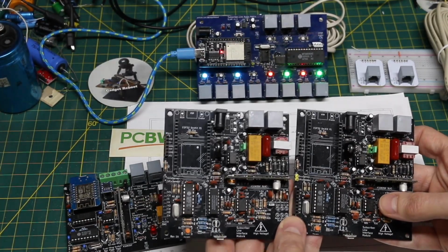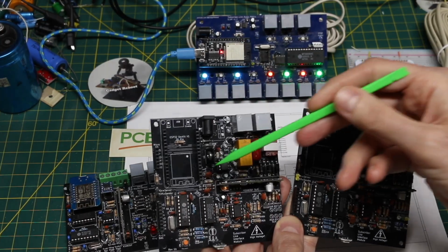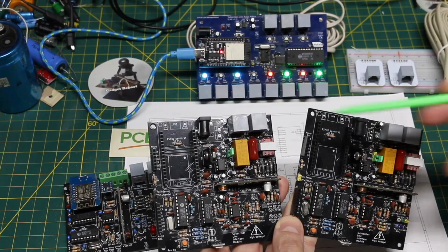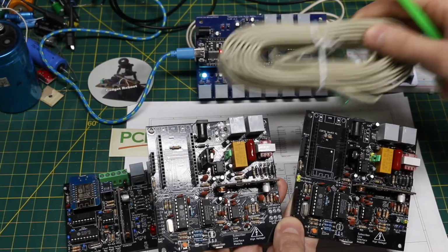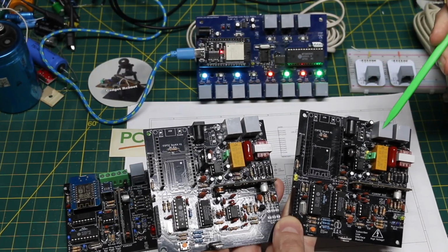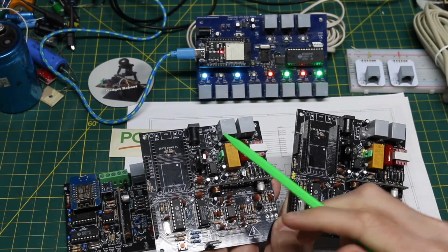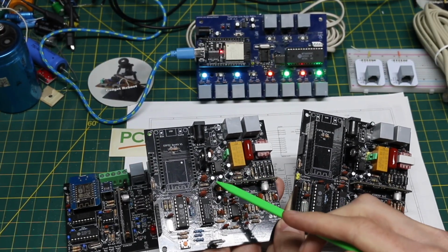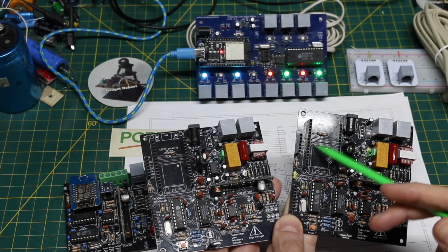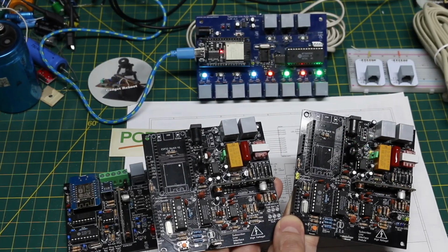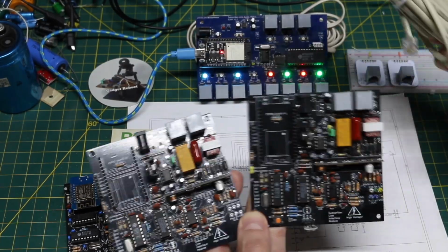And although this uses ESP32 plugged in on these sockets, the actual phone audio connection is still a landline with a phone jack on each board. So there's a phone cable that plugs in board to board directly, and then the other jack on each board has a telephone plugged in. So when one phone dials a number, it will wirelessly communicate with the other board to find out if the board is available to take a call. And if so, then it closes relay contacts and makes a physical landline connection between the boards.